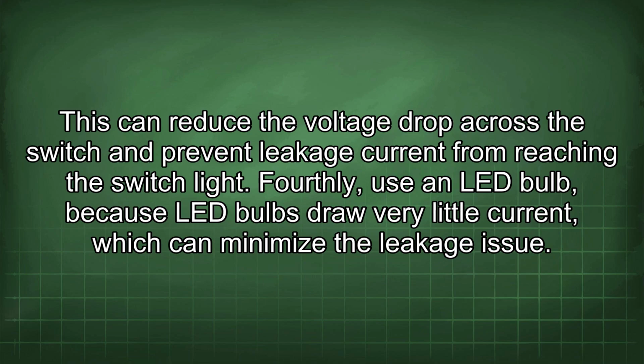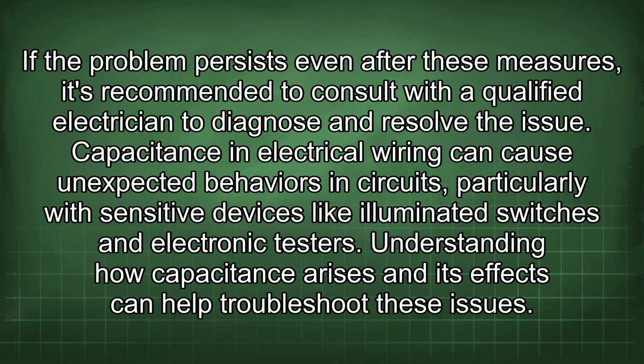This can reduce the voltage drop across the switch and prevent leakage current from reaching the switch light. Fourthly, use an LED bulb because LED bulbs draw very little current, which can minimize the leakage issue. If the problem persists even after these measures, it's recommended to consult with a qualified electrician to diagnose and resolve the issue.